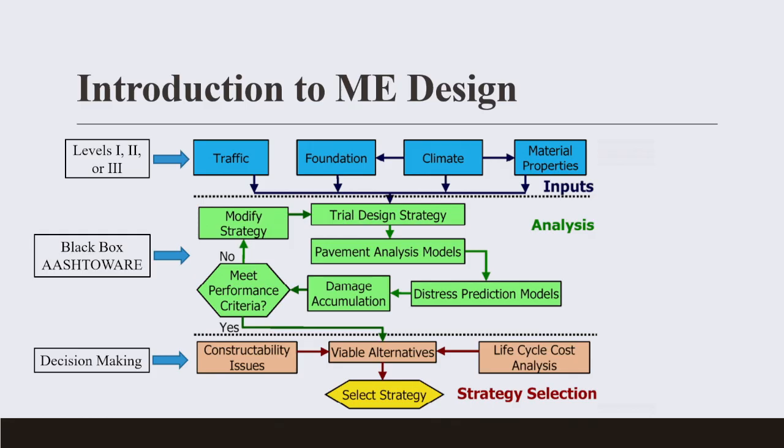Remember, in your typical mechanistic design, it will give you only the thickness of pavement, am I right? And give you elastic modulus, am I right? In Road Note 31, it will also give you thicknesses, and that's all. And you now have to go back and do the mix properties. This system will now even give you the mix properties.